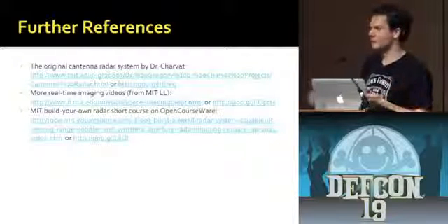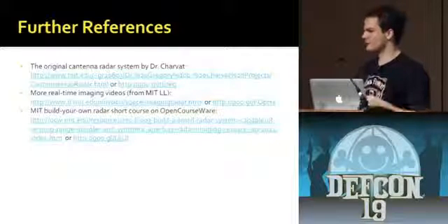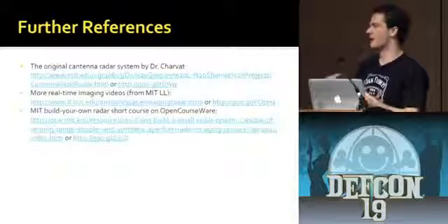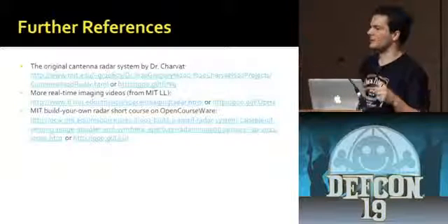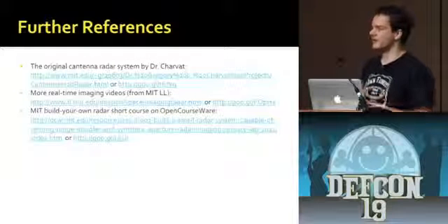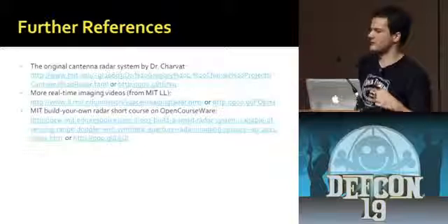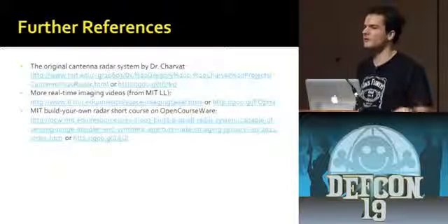So you could go up to 5 gigahertz. It would be a little harder to find parts. Basically, as you go up in frequency, the parts just get a little more expensive. Or as you get even higher, they can get a lot more expensive. But the big thing you want in a system like this is wide bandwidth, because the bandwidth is what's giving you that spatial resolution and the time resolution.